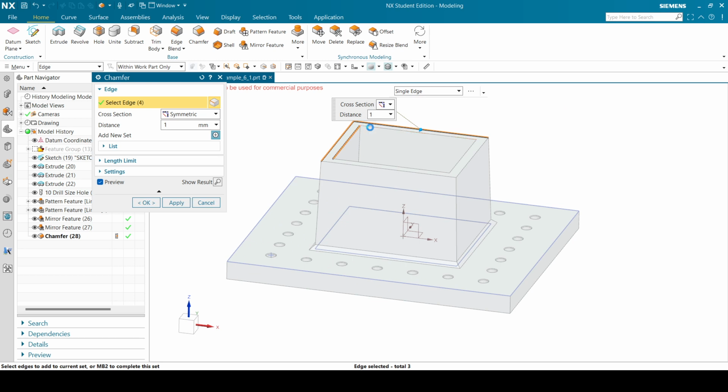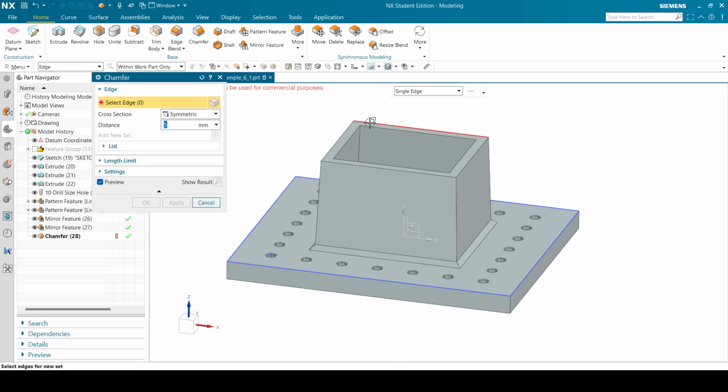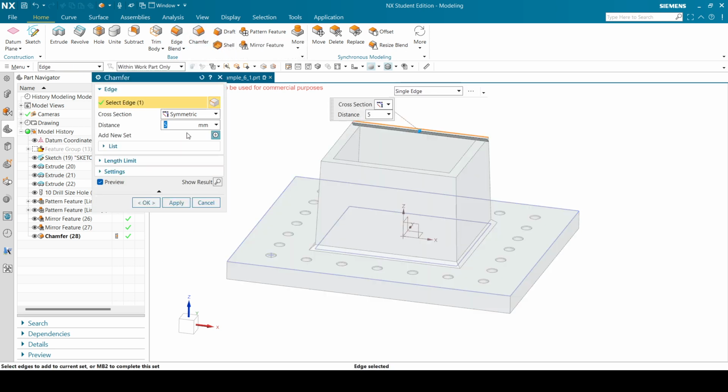all these protruding edges. And you can do this in one fell swoop. Don't, bloody thing. Okay, I accidentally clicked on something, so I'm just going to start over, and this should be 1mm, not 5mm. So let's try that again. Okay, so if you accidentally select something and you want to unselect it, hold in Shift and click on it again, and it will unselect.